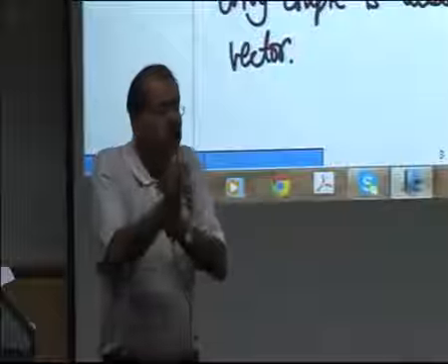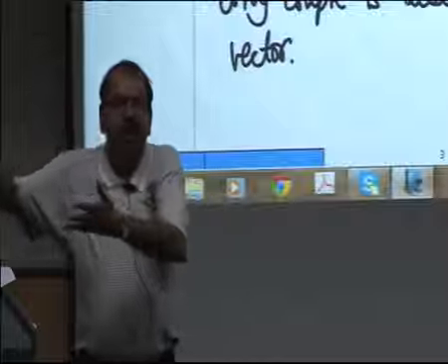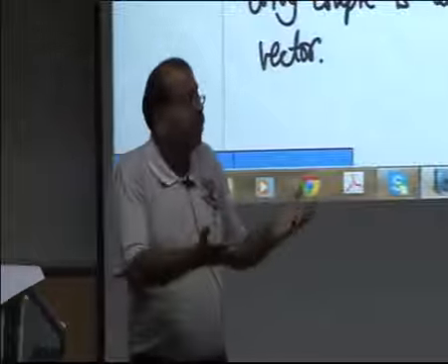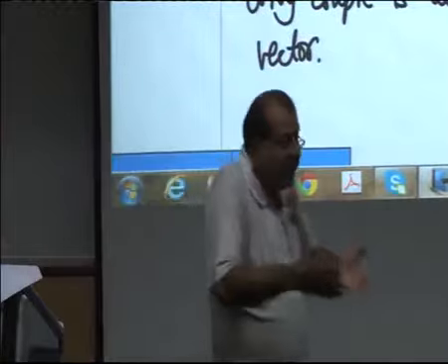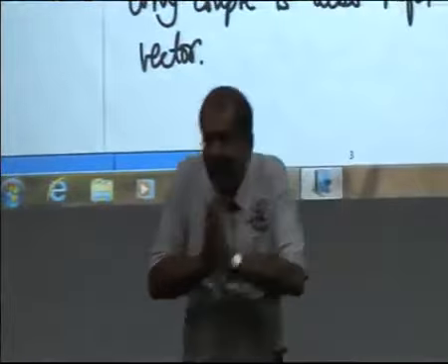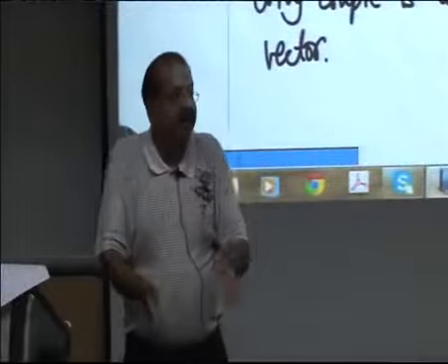So the best thing in three-dimensional problems is you calculate the position vector of each of these points, and you write the force as a vector. And wherever you have to find the moment, you just take Ri cross Fi. So you just individually, mathematically take the cross product and find the moment, and then you will get it in vectors.